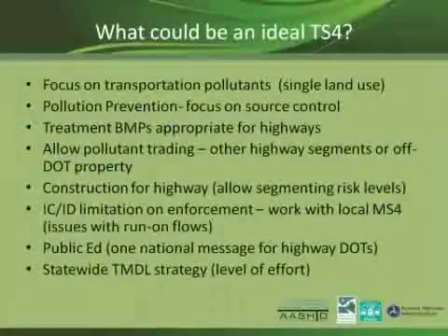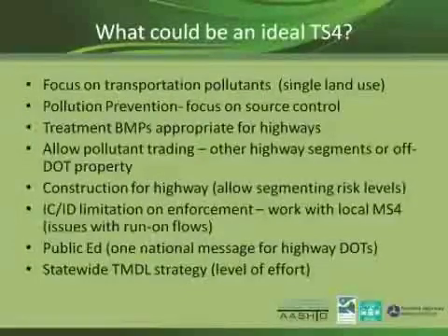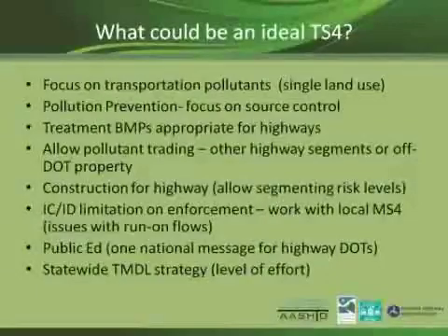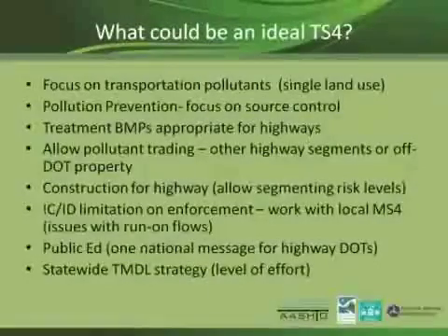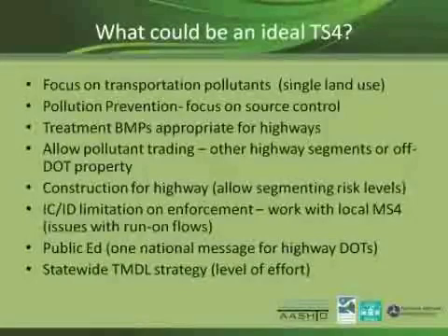So working with some of these challenges and these drivers, what would be an ideal TS4? Well, we think that we could focus on transportation pollutants, because we are a single land use, and the things that we know that we can work the hardest at eliminating. Pollution prevention, focus on source control. This can provide a bigger water quality benefit compared to costly structures that cost a lot to build and maintain. Treatment BMPs appropriate for highways.